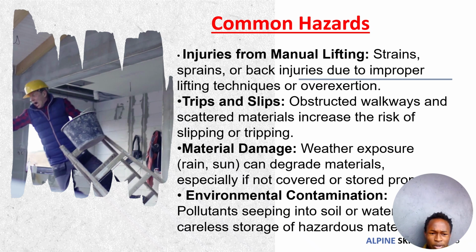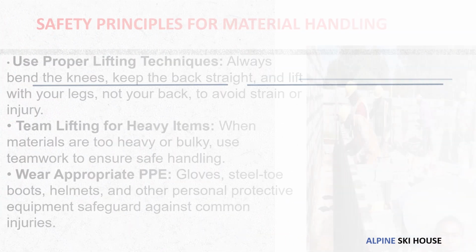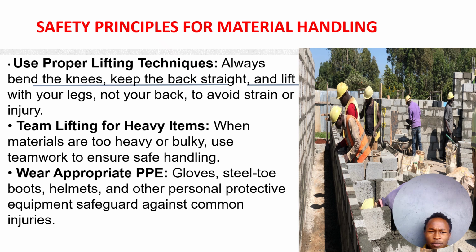So proceeding, we have principles for material handling. You should use proper lifting techniques. That is, instead of carrying cement bags with your backs and hands, you should use wheelbarrows, you should use lifts, you should use any other mechanical aids that are there, instead of using your bare hands. There's team lifting for heavy items. When materials are too heavy or bulky, you use teamwork to ensure safe handling.